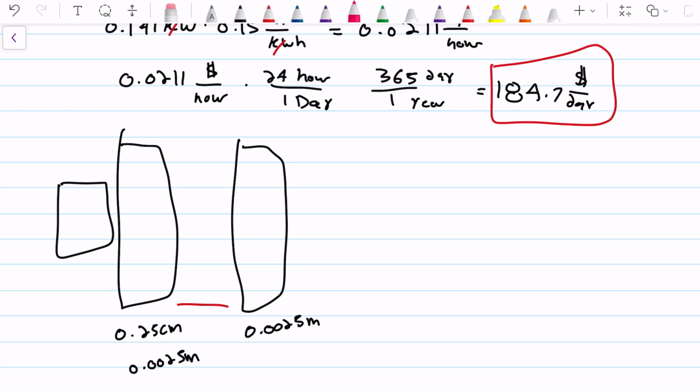Okay, so it's going to be linear, which means we're not going to use an h value. We're going to want to know just the k of air, which I have that value. Here, I'll write over here. k of air we will call 0.024. You can just look that number up if you didn't have it. And then essentially this is just like another solid. So now what we've got to do is just recalculate.